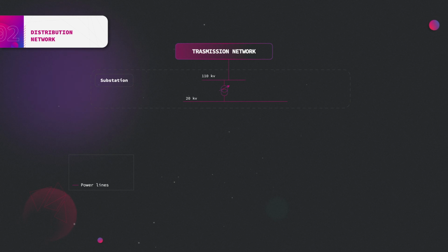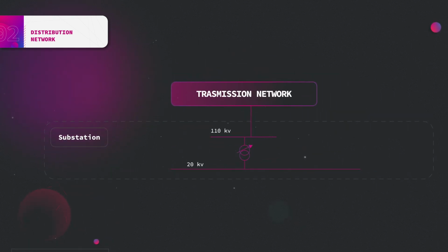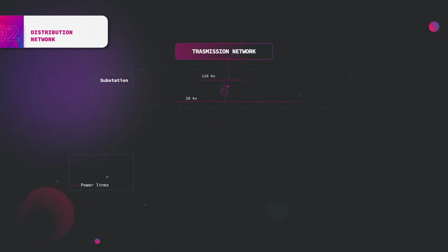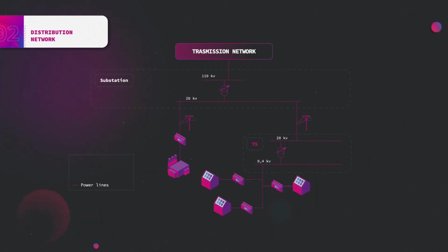The transmission network must be designed to withstand disconnection or malfunction of any element in the system without interrupting the supply and maintaining adequate power quality. Power transformers at substations closer to populated areas step down voltage, typically to levels below 110 kV, which indicates the beginning of distribution network. Distribution network supplies bigger industrial consumers and many low-voltage networks in the area.